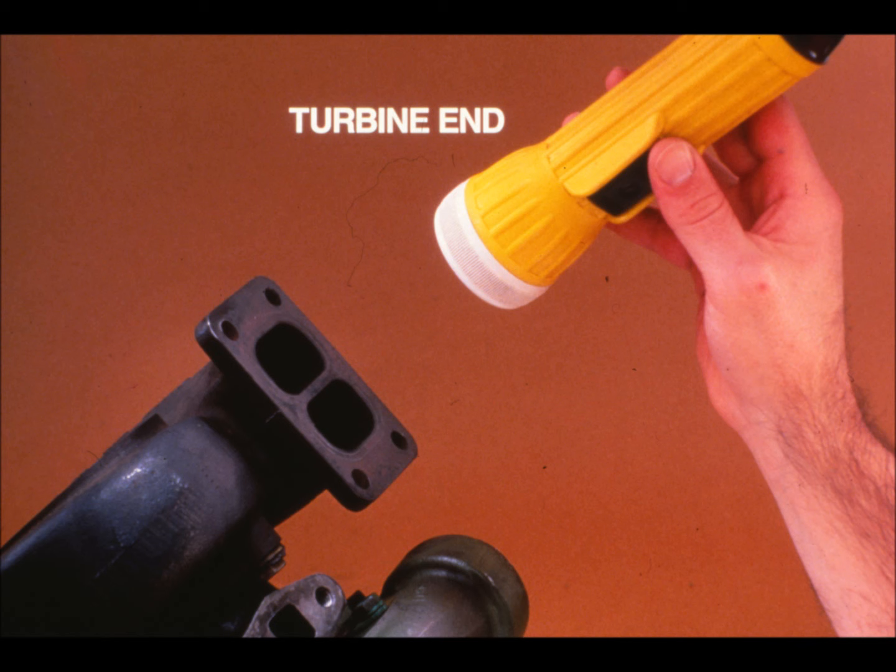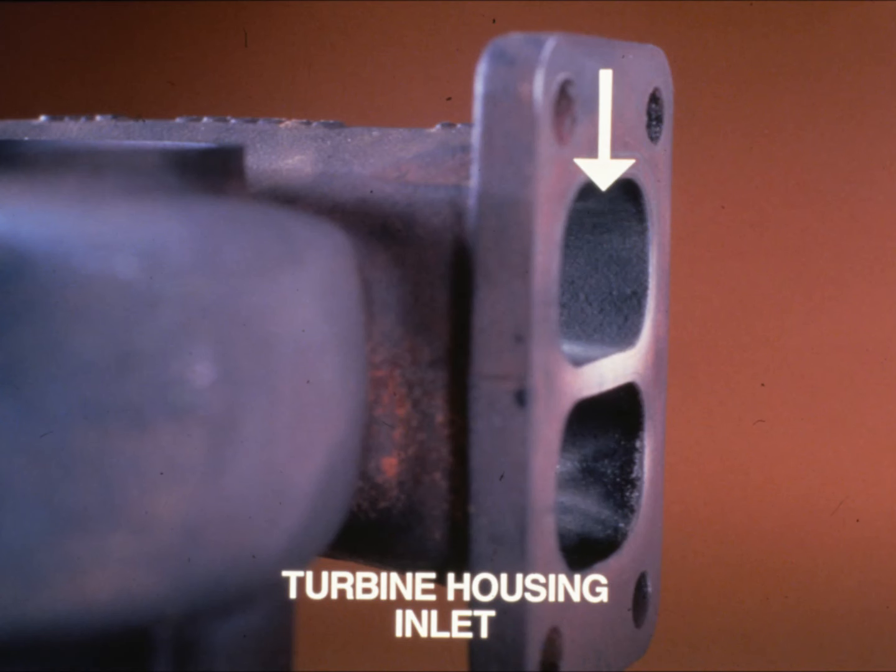Steps 3 and 4 of the inspection involve the turbine end of the turbocharger. Step 3 is checking the turbine housing inlet. This is where exhaust gases enter the turbine housing. The center dividing wall provides a steady flow of gases to the turbine wheel. It must be in good condition.